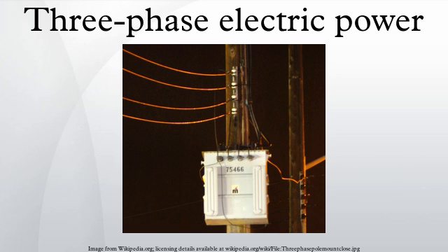Balanced circuits. In the perfectly balanced case, all three lines share equivalent loads. Examining the circuits, we can derive relationships between line voltage and current, and load voltage and current for Y and delta connected loads. In a balanced system, each line will produce equal voltage magnitudes at phase angles equally spaced from each other. With V1 as our reference and V3 lagging V2 lagging V1, using angle notation, we have these voltages feed into either a Y or delta connected load.